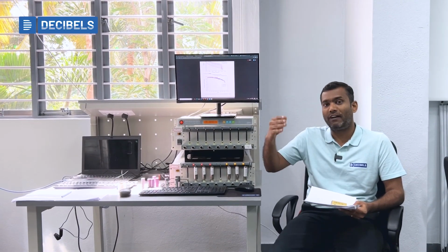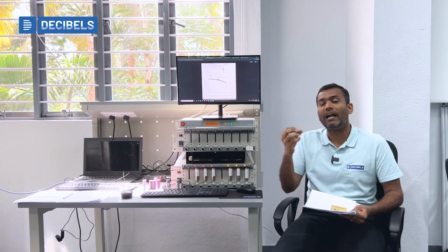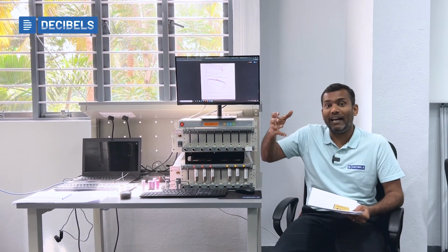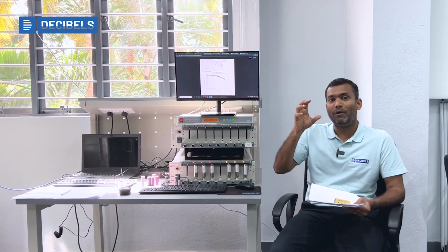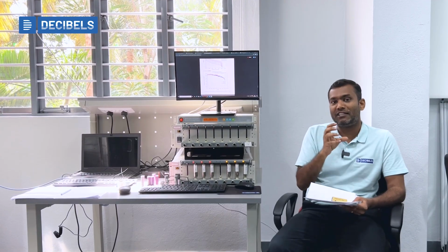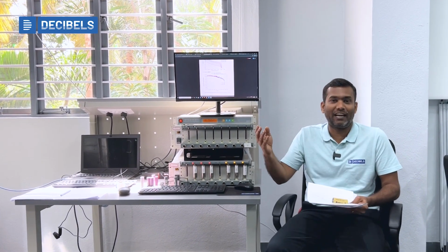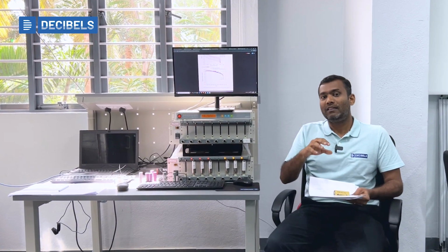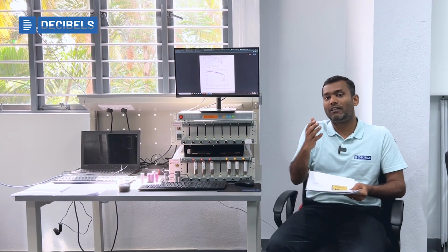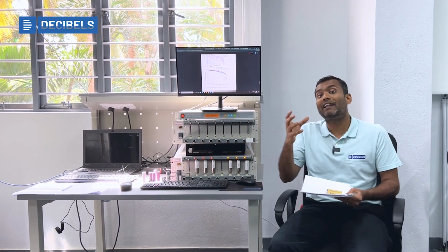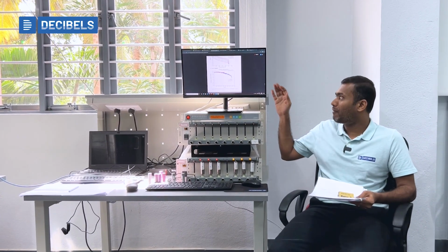And also for various different conditions, let's say you're developing a VCU functionality where you want to understand how the motor should derate depending upon the capacity output of the cell and its age. We will be able to write functions which will capture the intrinsic nature in such a way that the vehicle doesn't cut off after 500 cycles. The derating functions will take care of how you should limit the performance of the cell or the motor so that the inherent nature and functionalities of the battery are captured. Henceforth, to analyze all of these details, we perform a capacity test.